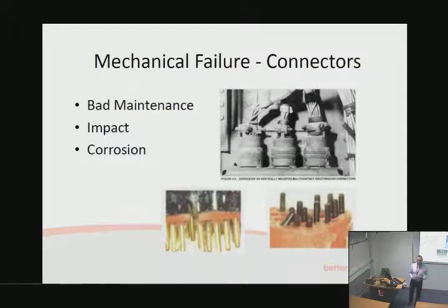In my experience in electronics, when something goes wrong, the first thing you do is check all the connectors. We all know that. Is it plugged in at the wall? Is the socket thoroughly pushed into our device? Is it working? And when things break, they break badly. And often when things are out in the field being used, they can cause all sorts of failures to occur. Connectors can degrade quite subtly if a pin gets pushed back or something like that. So that's another example of how the mechanical world encroaches on our apparently perfect digital electronics world. And you can't overlook that when you're designing your stuff.